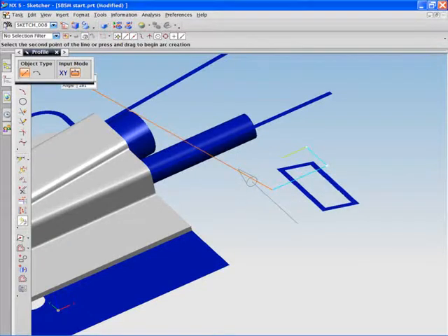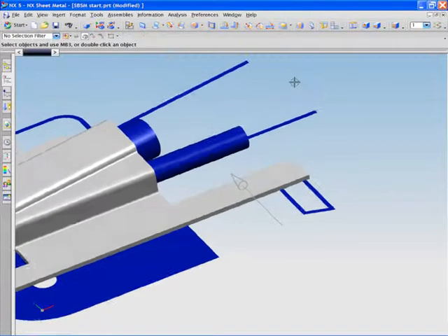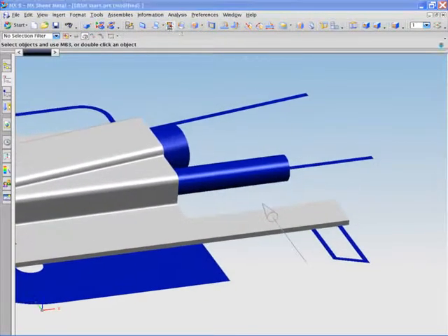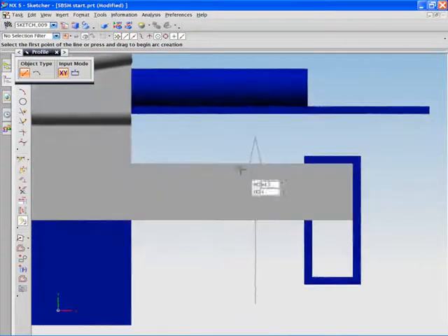You might well see an alert appear stating that the preview has failed. This is fine and good feedback. In this case, the direction of the flange width is incorrect. It is easy to remedy this by reversing the direction.